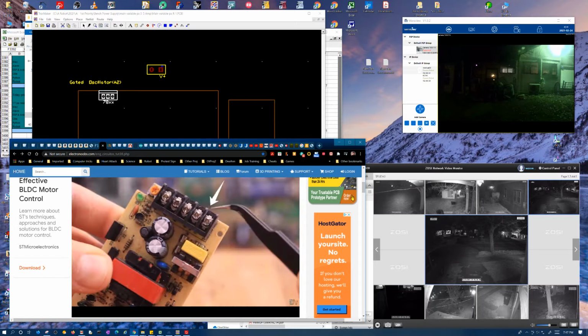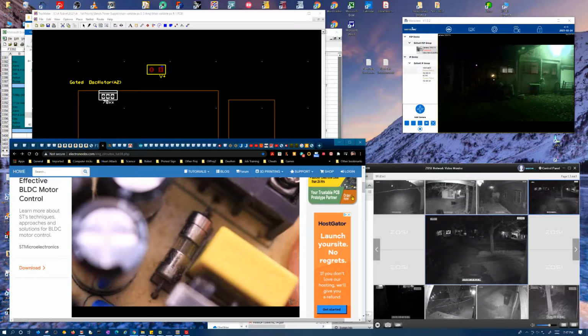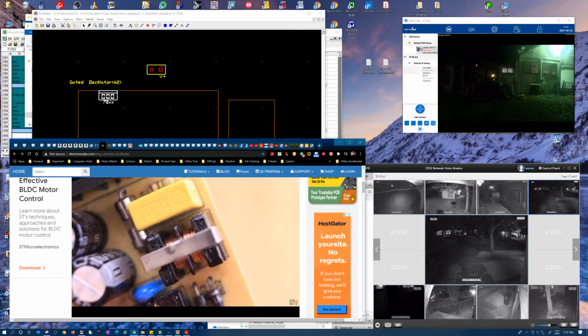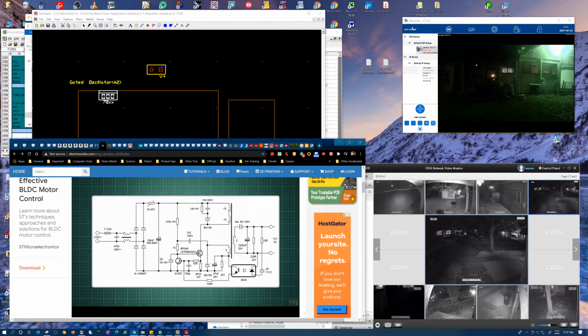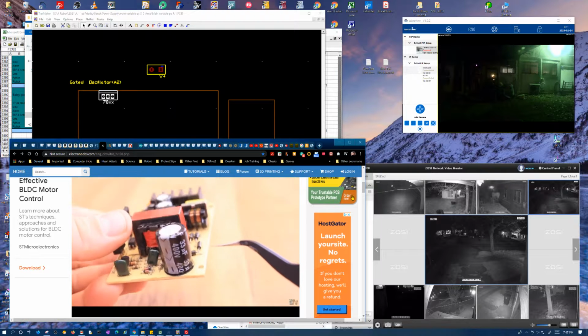We have the main input here of 230 volts AC. We pass that first to a fuse for safety. Then we place a capacitor and a choke to block the higher frequencies. We can see these components on the schematic as well. And as you can see, we then pass the 230 volts to a full bridge rectifier. We can see 4 diodes on the power supply PCB as well, and that is our bridge rectifier.